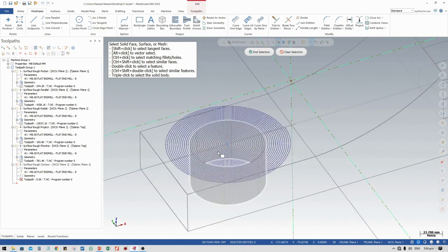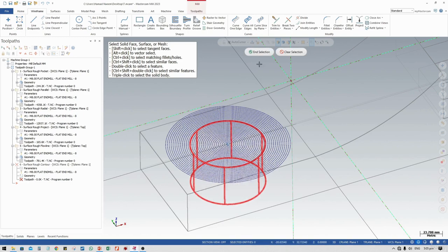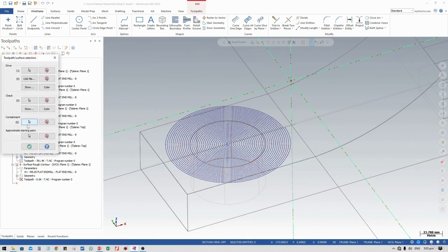We have a hole and we just want to contour that surface area, or we want to move the cutter peripherally to this surface or tangentially to the surface. Then we use this contour area. Let me select this area and machine that area. Okay. We already have the inside, which was made using the pocket operation. So click OK, and we have the containment option.